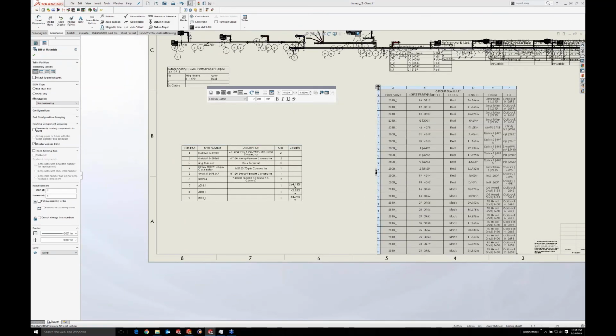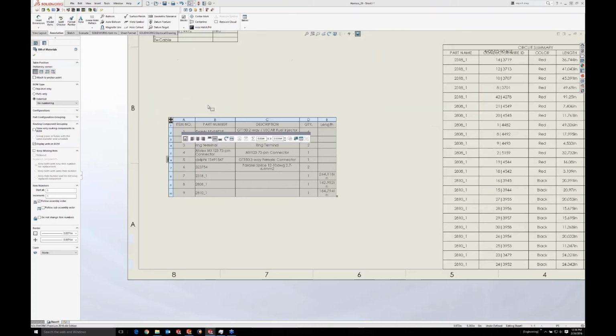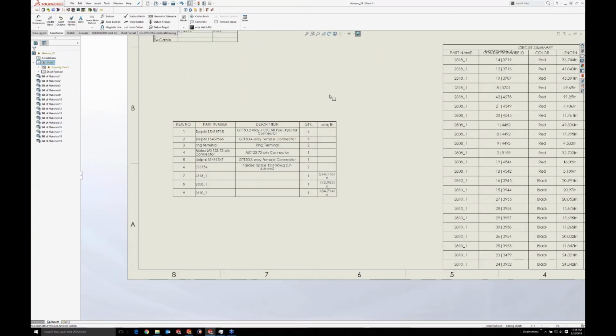Over here, this is our actual bill of materials, and you've probably heard the term SOLIDWORKS Electrical electromechanical BOM, combined BOM. Oh my gosh, it's wonderful. Well, in a simple thing like a harness, this is that combined BOM. So we have some Delphi connectors, we have a couple of ring terminals, we have a quantity over here, and then we have these 3 wire types. So these are wire styles, and we can replace these internal IDs with their actual names if you'd like. And these are the exact lengths of how much wire was used in this harness.